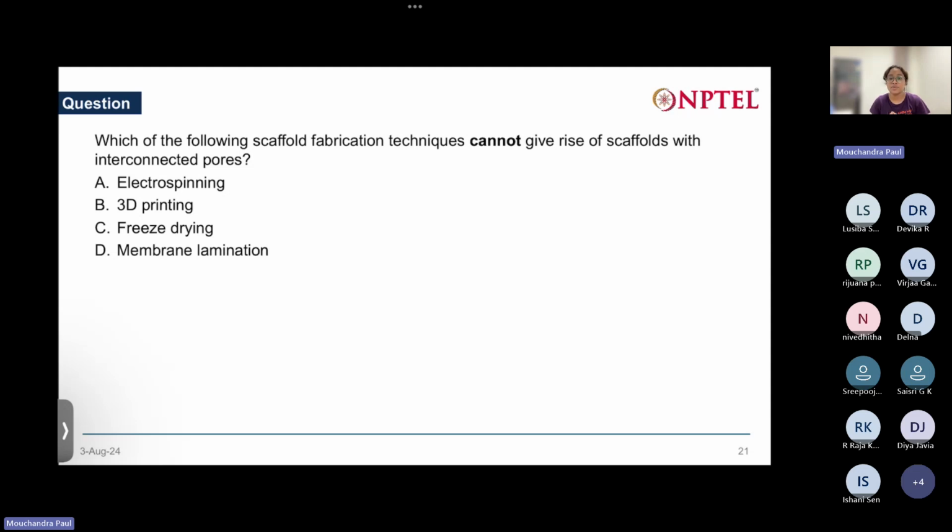Okay, so then under these conditions, the process of sublimation starts. Means directly the water molecules convert from ice crystals to vapors. There is no intermediate liquid phase there. Okay, and this is only possible when we keep the sample at a very low vacuum and very low temperature. This is called freeze drying.